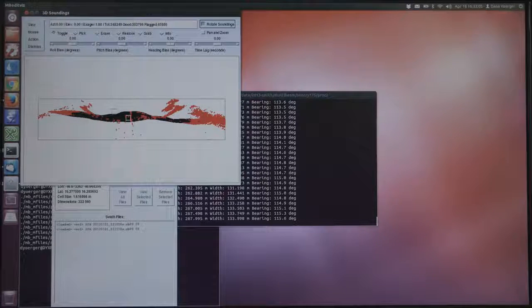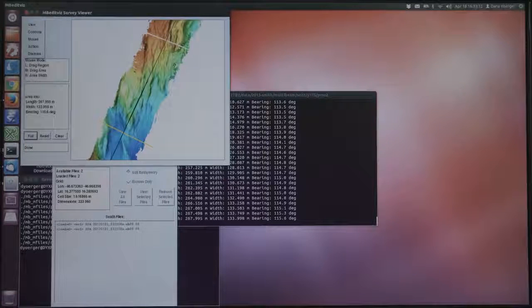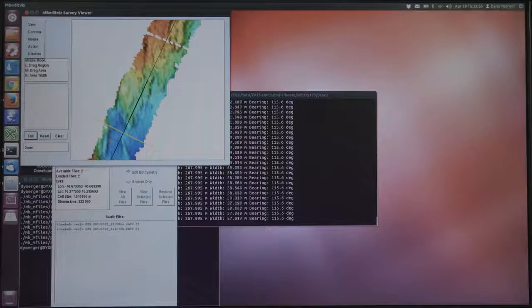This is very useful, except that we have way too much data here. That box that we cut is too thick, so we're going to have to reduce its width. And we do that using the mouse command right button. We're in pick area mode, and the mouse command we want to use is this right area width. So we go up to the top of the screen, we right click and we pull down, and it's actually reducing the width of the box.